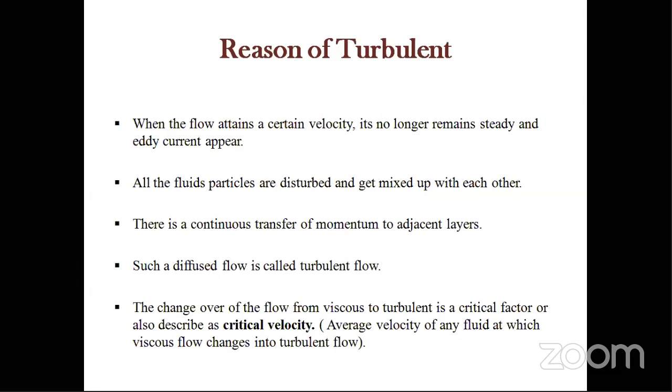So all the fluid particles are disturbed and get mixed up with each other. So there is a continuous transfer of what? It is momentum. Momentum means the velocity. Velocity increases means momentum increases. And when momentum increases, the parallel layers, meaning the adjacent layers, are mixed with each other. The particles are distributed in the whole water, and the whole water gets colored, and such diffuse flow is called turbulent flow.